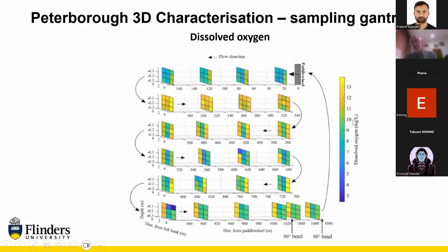It's oversaturated, probably 150% saturated in dissolved oxygen. And we thought, when it went through the paddle wheel, was it being deoxygenated? Because all of a sudden the oxygen's dropped from here. This is a body of water that's coming from here, going through the paddle wheel and back down that channel. And what it looked like was that the oxygen was really high here, and maybe the paddle wheel with its rotation was deoxygenating the water.